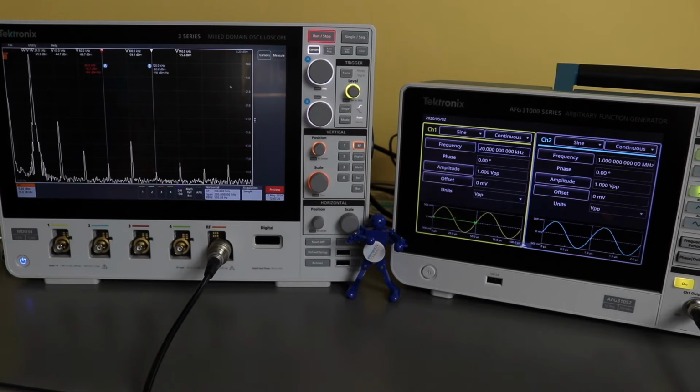So what I'll do is pull up the spreadsheet that shows the calculation, and you'll see the specification from Tektronix is 0.2%. I'm getting about 0.4%, and the culprit seems to be this second harmonic here at 40 kHz, which is about minus 44 dBm on this reading.